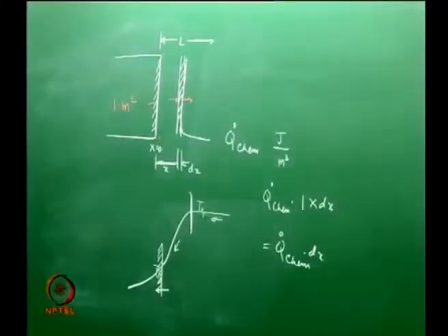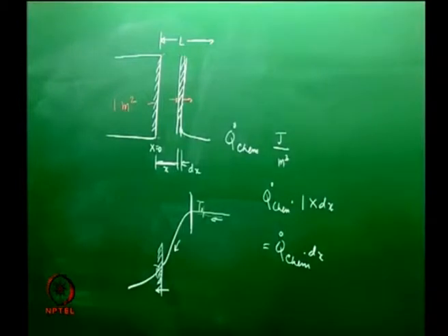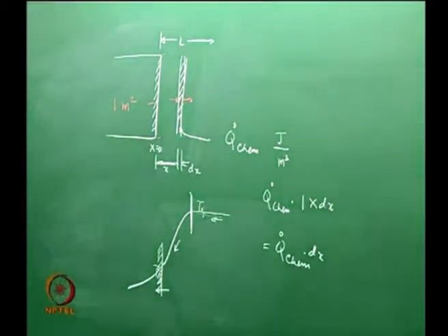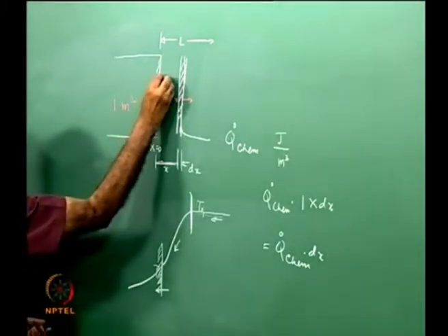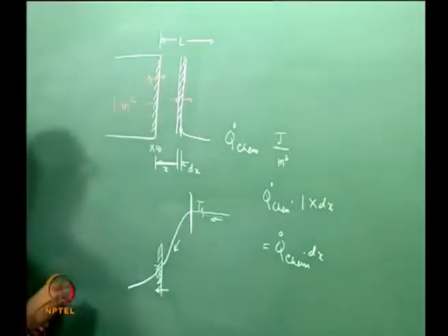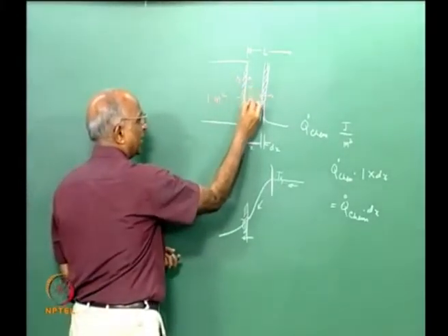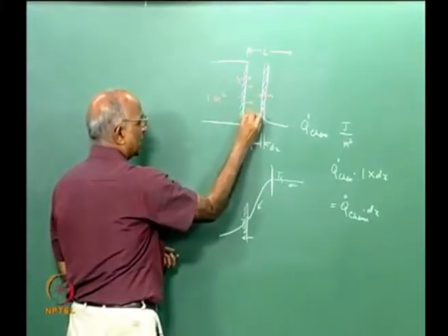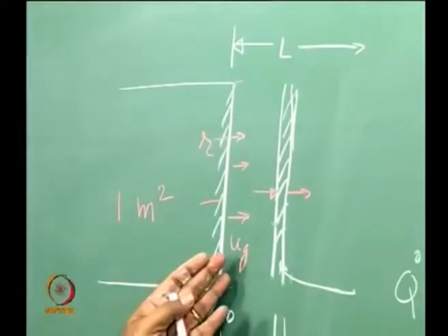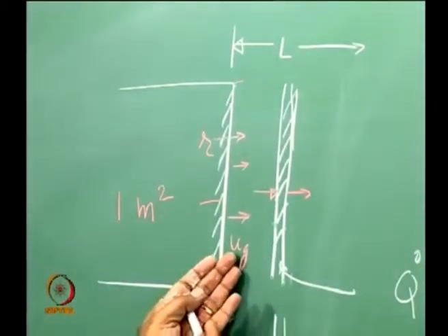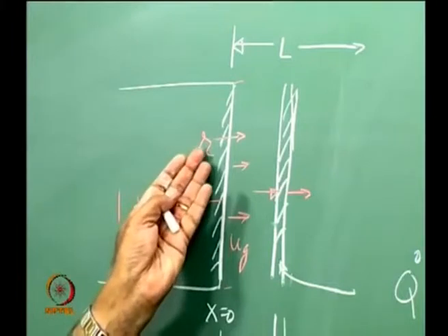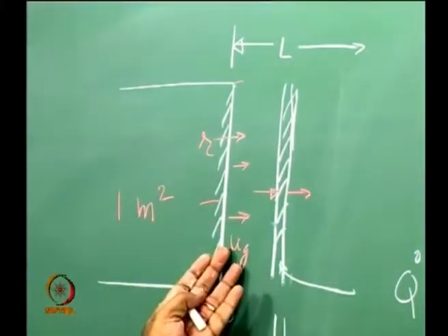Is there anything else I have to consider in a heat balance? We are telling ourselves, well, the propellant is burning, consider this surface to be the frame of reference. With respect to this surface, the propellant is burning, let us say at a value R. What happens when the propellant burns? Hot gases are getting generated. Let the gas move at a velocity ug, and this ug will be different from R, because R is for a solid, ug is for a gas.